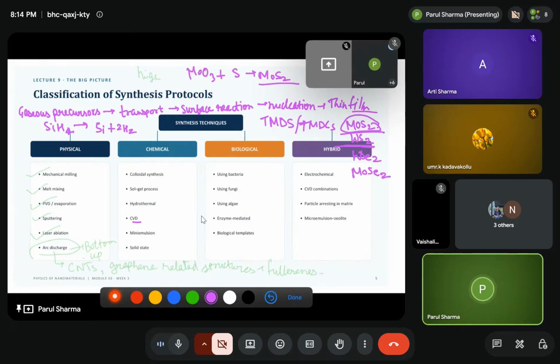For the formation of thin films using CVD, we control whether we are working in an argon environment or nitrogen environment, how many SCCM of oxygen is needed, what the ramp time is, what the stabilizing time is. All these things happen, and using these the size and shape of the thin films is decided.